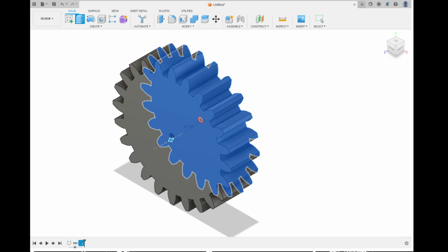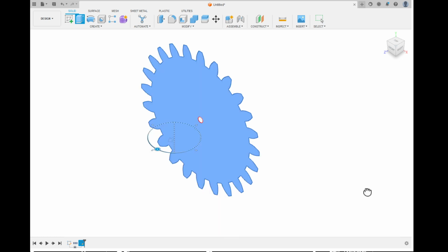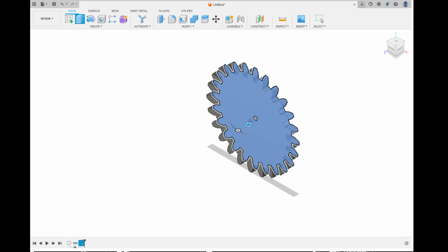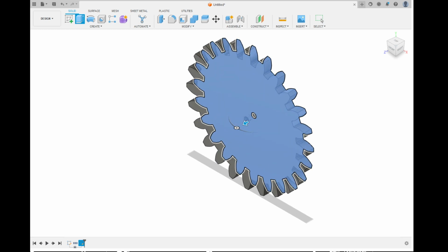What we're also going to do is adjust this angle over here. Let's make it 20 millimeters thick. Right, so we can make it 20 millimeters thick, and we want to change this angle by changing this knob over here, this circle over here, to make a taper angle, so we can have it angled at 45 degrees.